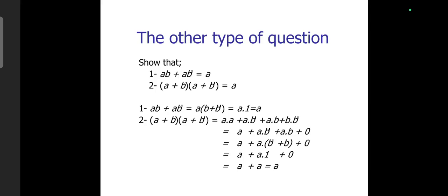For example, suppose a designer has created a circuit using AND gates and OR gates. During manufacturing, it may become more economical to implement the same circuit using only NAND gates. So at this point, De Morgan's theorem has become extremely useful because it provides the mathematical relationship needed to convert expressions between equivalent forms. So let us consider (a plus b) the whole bar.